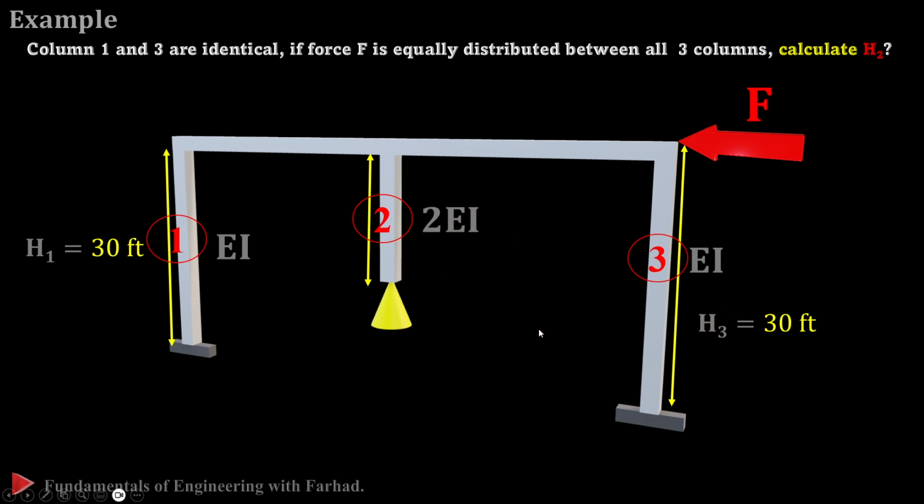If you remember, we solved it in the parallel example, where we said that in a parallel situation the force is distributed between the columns based off their stiffness.